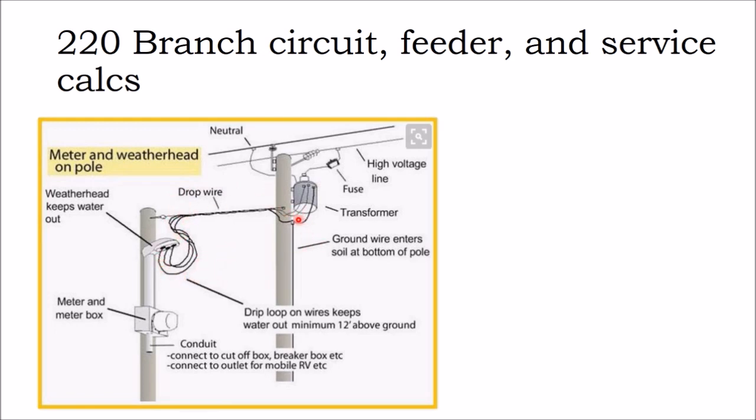Sometimes you might look at these overhead cables and think, wow, why are these wires just kind of hanging out here? Sometimes they're taped off, but they have to hang out because right here it's called a drip loop. When it rains, water comes down the line, and that water could go straight into the metal and then drip down in the meter and short it out. So electricians install a drip loop to keep the water out of the weatherhead.